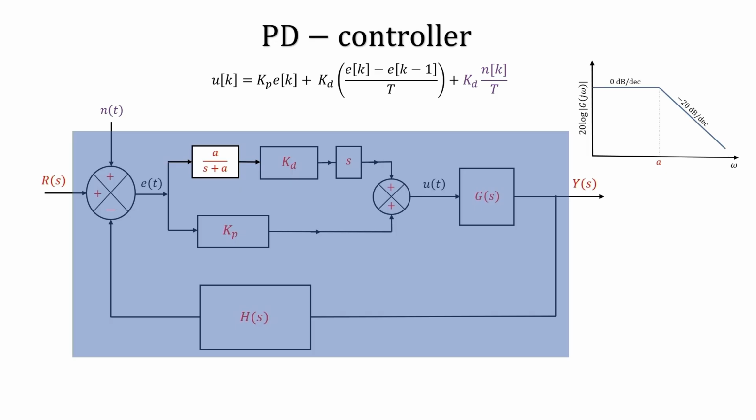Now, look at this Bode plot. It means that at lower frequencies the output will not get affected, but at higher frequencies the output of this block will get attenuated. If you look at the Bode plot, that is what it means. These are the magnitude of the output, and you can see the magnitude decreases as the frequency increases.